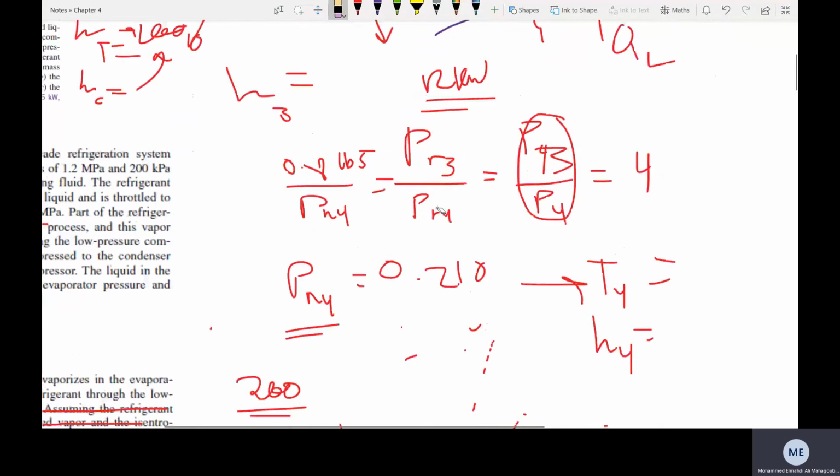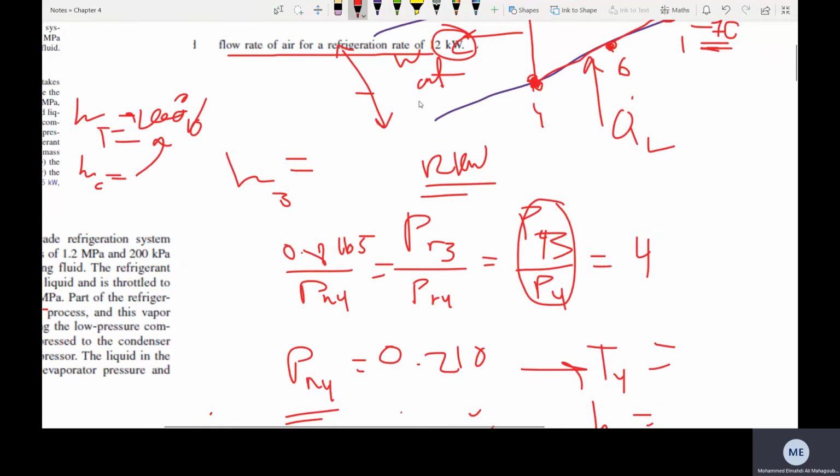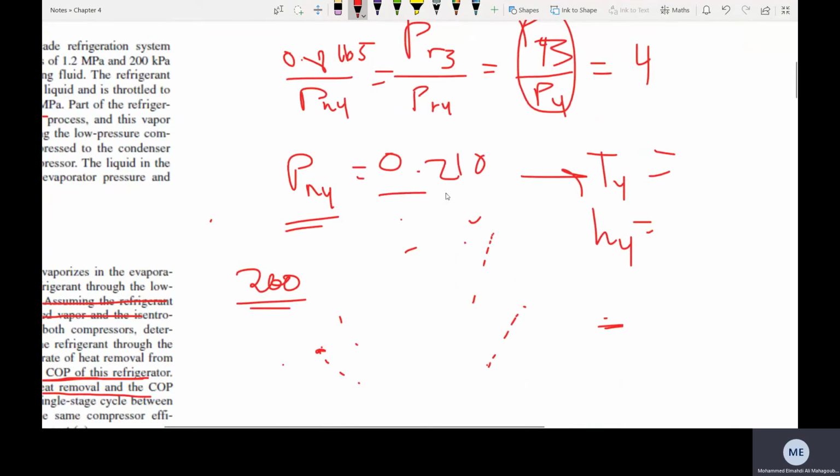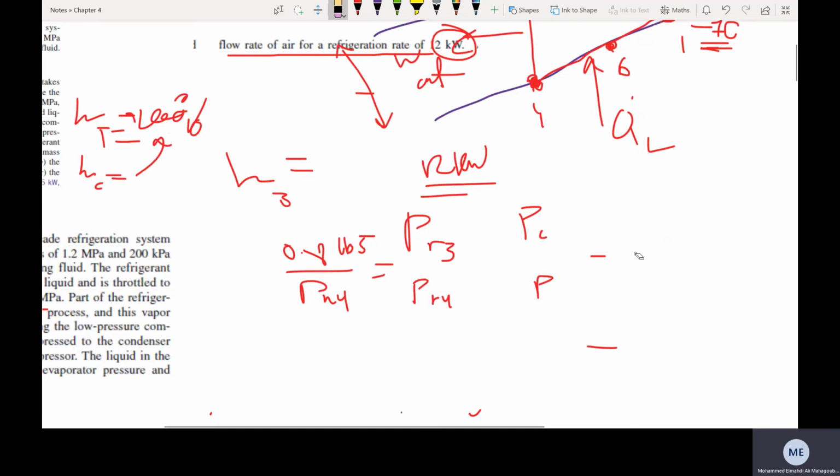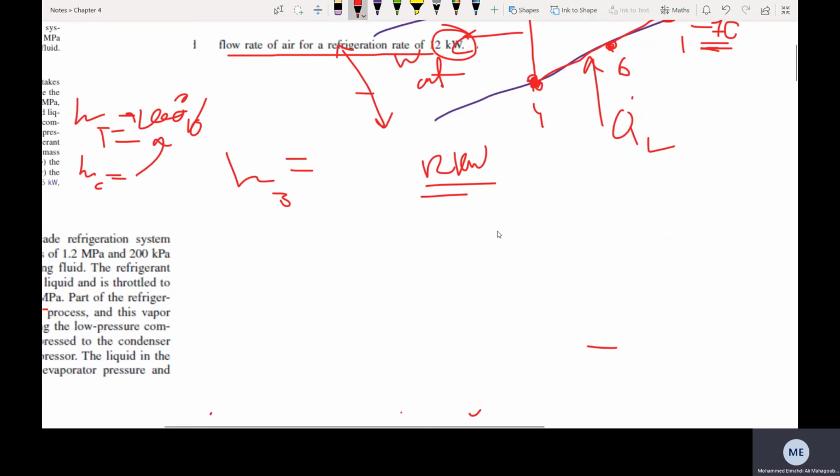So I just wanted to show you a demonstration, but it turns out that our temperature is lower, so if you want to go with this pressure ratio, you need other air tables. I guess I have some air tables that go to that point, but let us use the tables that are in your textbook. So you need to use the T-P-K relationships now. We know the relationship for the pressure, and we need the temperature. So the one that goes for that is which relation?